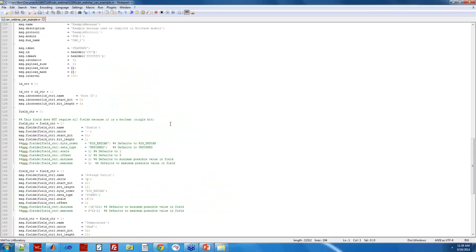But if you're working with a non-MotoHawk controller, like a component you may have sourced that you want to control over CAN, you'd need to create these M files for each message for that component, and you may be interpreting a Word doc or an Excel spreadsheet or something, and there's definitely a lot of opportunities for misinterpretation there. Due to the way that people specify start bits and endianness, there's some room for interpretation sometimes with specs. They can be kind of ambiguous.